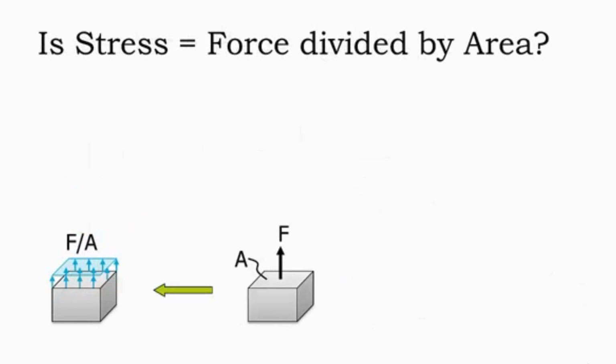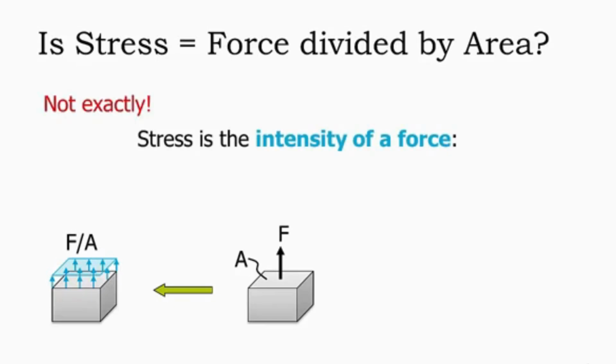Looking at stress in this manner, and looking at the units of stress, you might ask yourself, is stress simply force divided by area? Well, not exactly. Stress is actually the intensity of a force. And although force divided by area might be a nice approximation of what the stress distribution is in an actual case, stress is actually the limit of force divided by area as that area approaches zero.